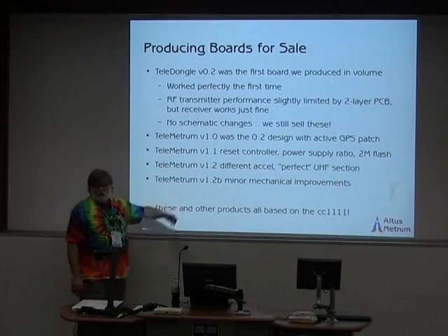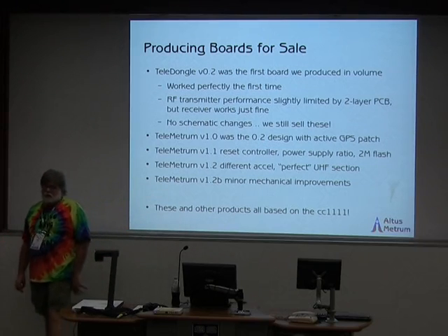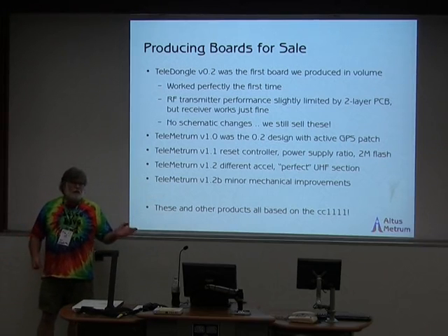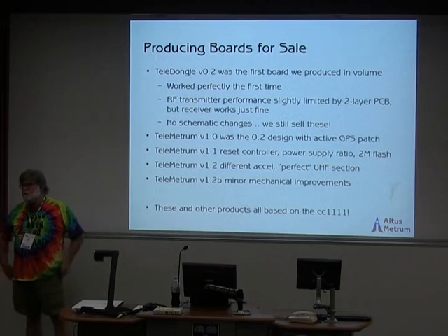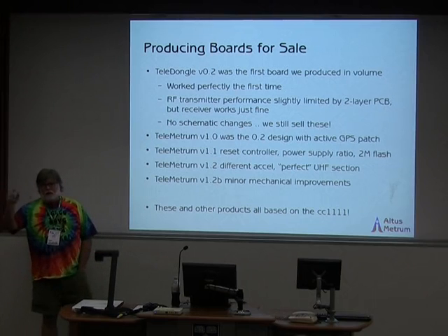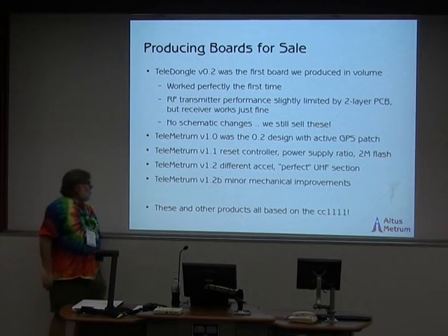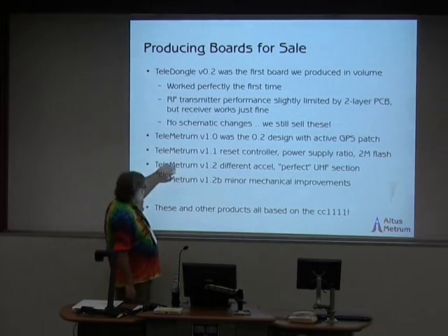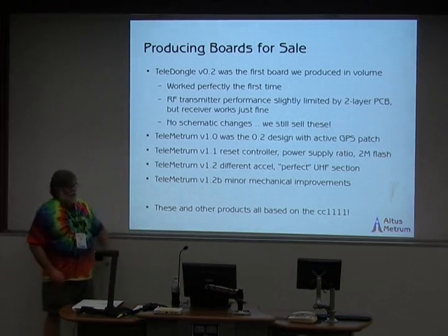On version 1.2, I never saw a board with less than 10.1. They were all somewhere between plus 10 and plus 10.5 dBm output. So that's the one where I finally got the filter design, the layout, and the component selection right to actually achieve what that chip's capable of. And we really like that design. The only changes on 1.2b,